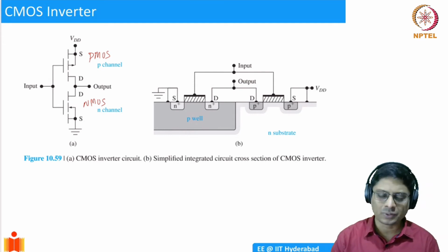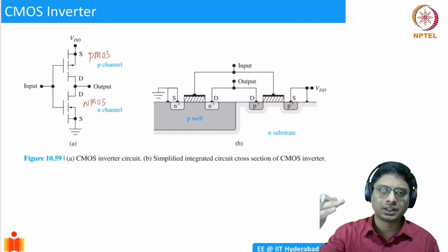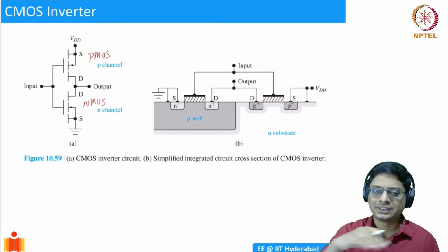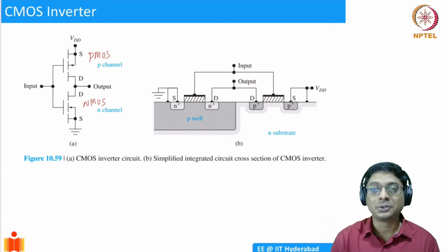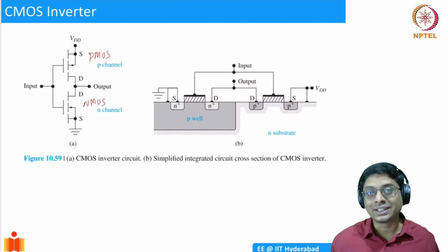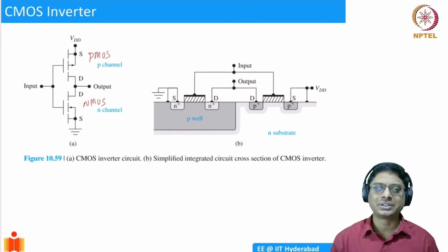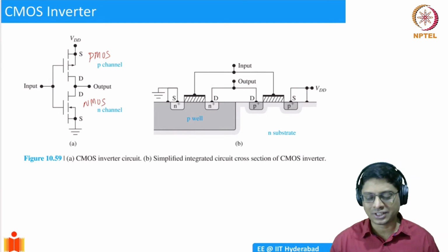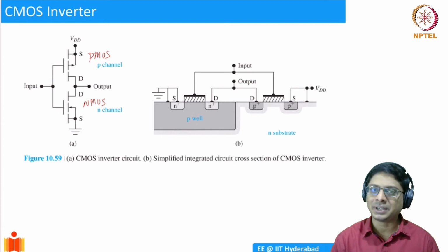Something similar happens. Once you make the basic device, you do what is known as metal layers on the top of the wafer. And there can be many metal layers, and then a lot of connections are made. Imagine, if you ever try to design a PCB with, let's say, 100 components, you would understand how difficult it is to do the layout. Okay, but now we are talking about layouts connecting, let's say, billions of transistors. So you're going to have a lot of complications. So there's a lot of planning involved in how to do the layout and all that. Okay, but anyway, it can be done.